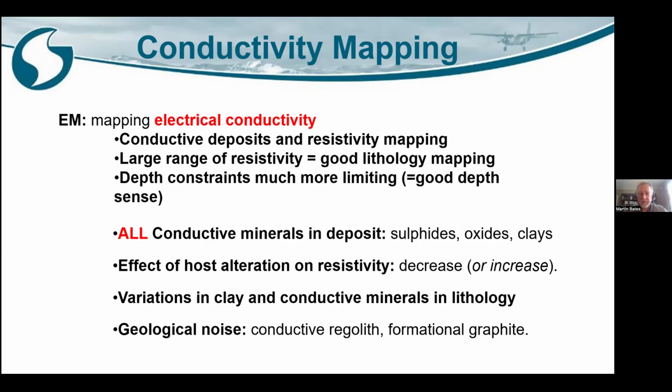If you're having problems with your aquifers being close to the sea and you're getting invasion of saline water from the sea into your aquifers, you can measure the saline to freshwater boundary because the saline water is higher conductivity, and you see that in the near surface data, so you can measure that too.